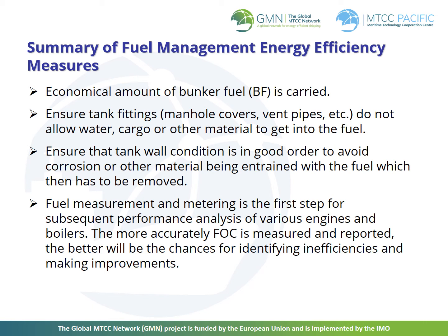Ensure that tank fittings such as manhole covers and vent pipes do not allow water, cargo or other material to get into the fuel. Ensure that heating coils are tight. Ensure that the tank wall condition is in good order, thus avoiding corrosion or other material being entrained with the fuel, which then has to be removed.